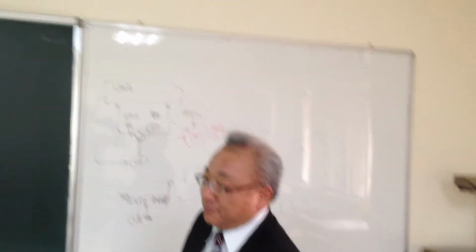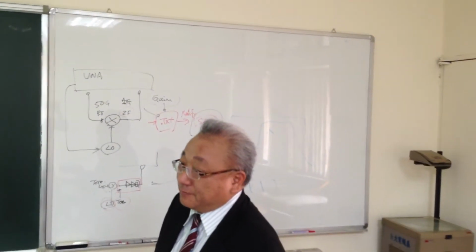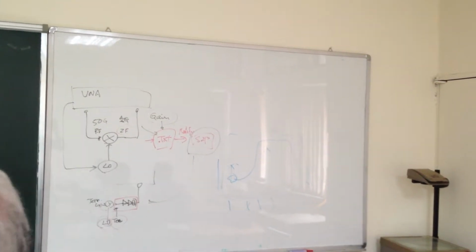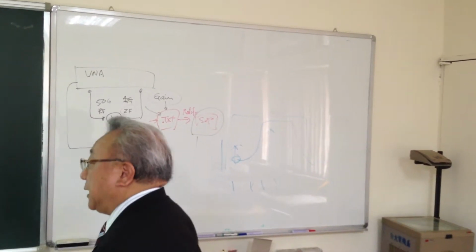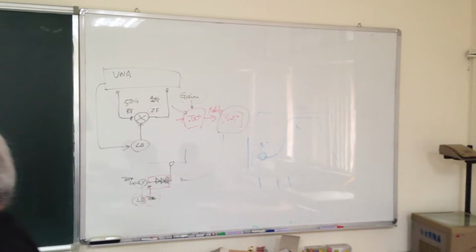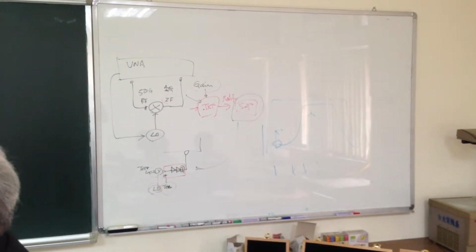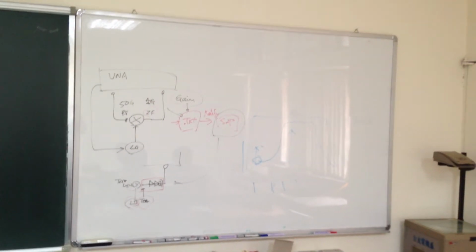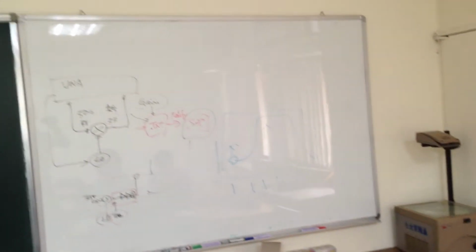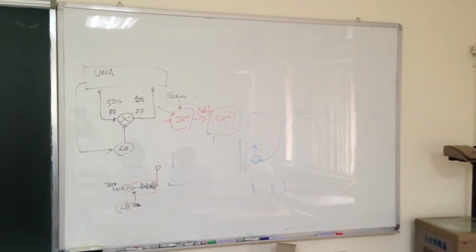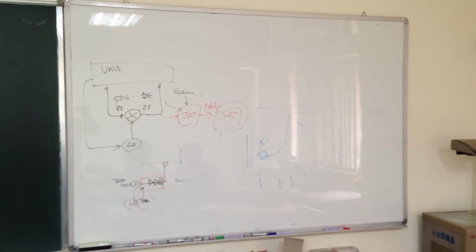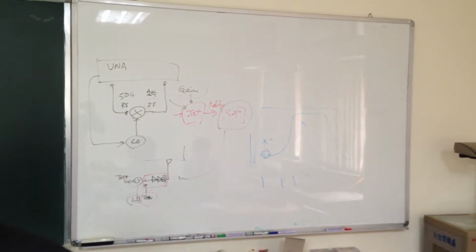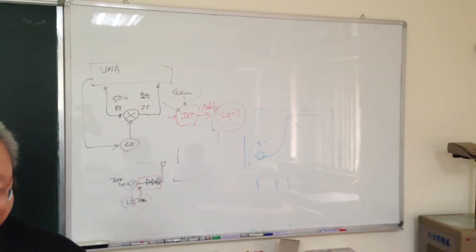What is the lowest frequency of our measurement? It's 70 kilohertz. So the noise figure at 70 kilohertz is reasonable. Reasonableness meaning it's accurate, if we use this measurement. So we have to check the accuracy at 70 kilohertz. Yeah, it's the same.